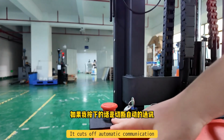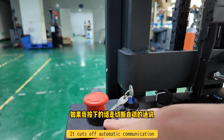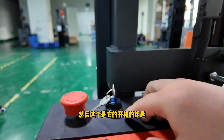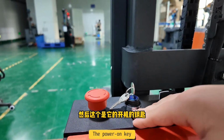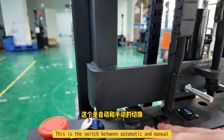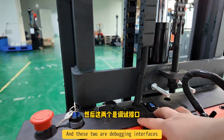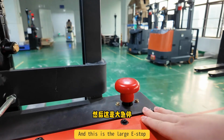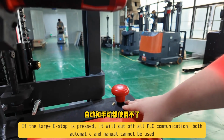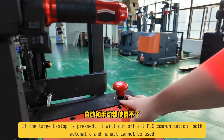If pressed, it cuts off automatic communication. The power on key. This is the switch between automatic and manual, and these two are debugging interfaces. And this is the large e-stop. If the large e-stop is pressed, it will cut off all PLC communication. Both automatic and manual cannot be used.